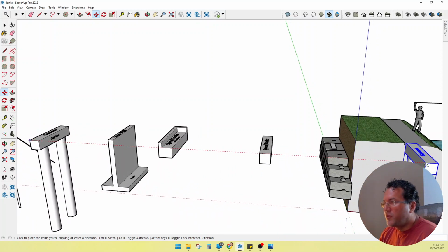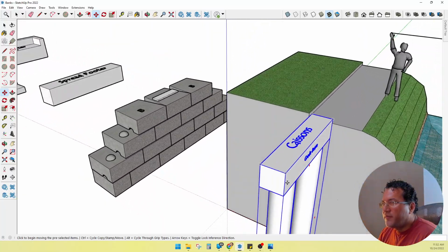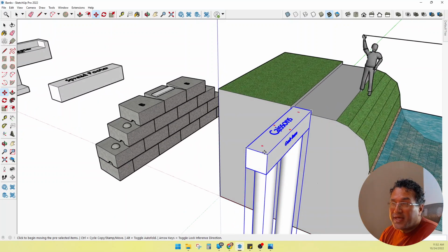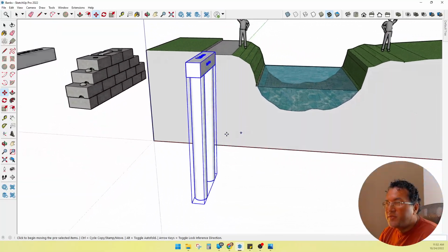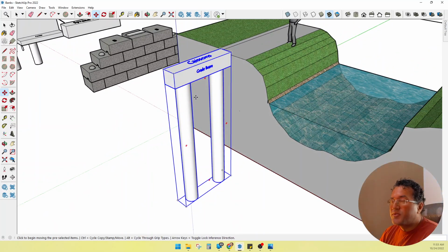So you have the cost of a traditional, and not really the grade beam. A spread footer and a grade beam are almost identical. They're almost identical in the size, 2 foot by 2 foot by 2 foot wider than your bridge, right? So this is the same, but now you have the added cost of these big, long caissons. So they actually get a crane out there. I'm sorry, a drilling rig to drill down there. These are 24-inch diameter holes. They can be 36, they can be 18, there's very different sizes, but for most private jobs, and even for government jobs, these are really a chore to build.